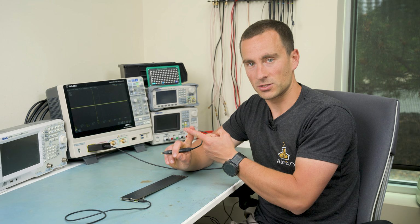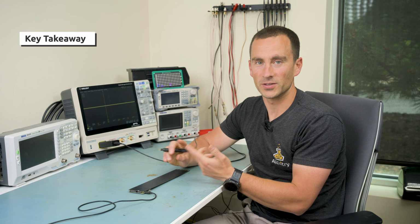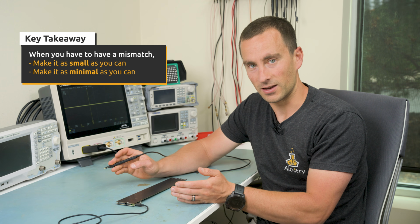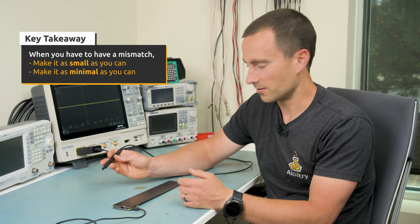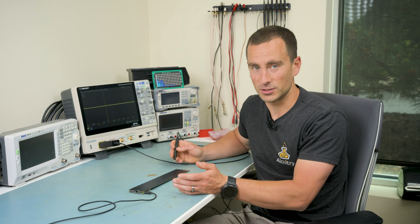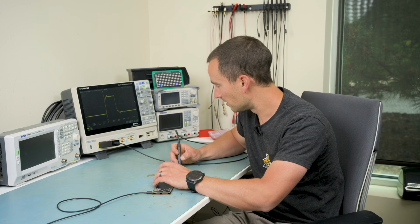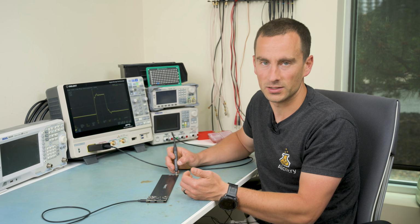The longer the mismatch, the worse it is. The worse the mismatch, the worse it is. So the rule of thumb to take away from this is when you have to have a mismatch, make it as small as you can and make it as minimal as you can. With that said, if your data speeds aren't that high, even with an insanely terrible mismatch, this would be a reasonably acceptable signal if you were only running at 100 megahertz.